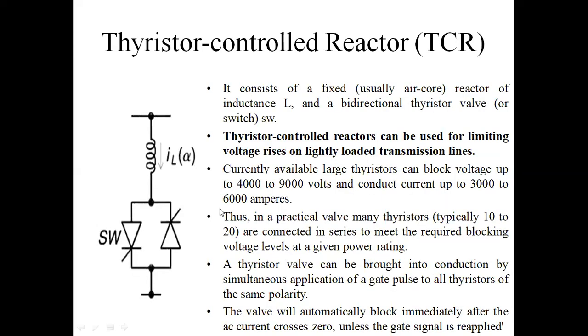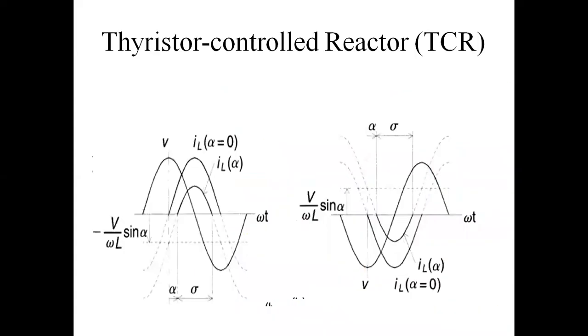These two thyristors are not operated like an ACVC. ACVC means alternating voltage controller. These thyristors operate from 90 to 180 degrees. Here the supply voltage starts. After 90 degrees, the current starts here. In this inductor current, the increasing time and decreasing time are both the same.